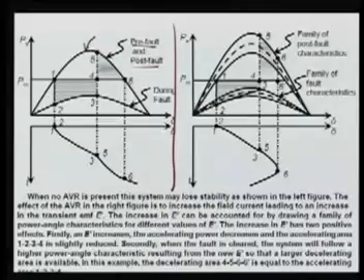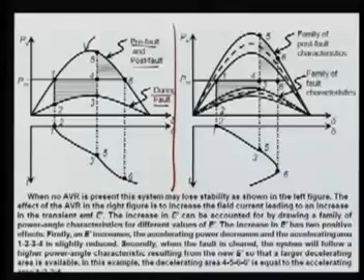During the fault, let's suppose we have this consideration, this curve. Now you can see, if you don't have AVR and by chance this fault is not cleared before the fault clearing angle, meaning your machine is loaded with PM, your operating point is 1 during the steady state. Once the fault has taken place at bus 1, it comes to this, because during the fault your PE curve is following this one.